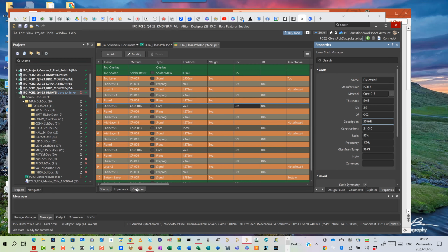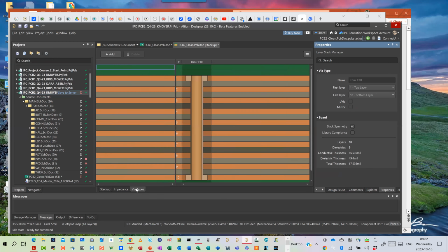Again, we're going to get into why this is in future weeks, but for the purpose of building our stackup up here, I'm going to demonstrate right now and explain why I'm doing this later. So within the Stackup, the only one you can never delete is the full through via. Every Altium Stackup requires that you allow for the complete full through via from top all the way to bottom. But then I can add any other new vias I want.